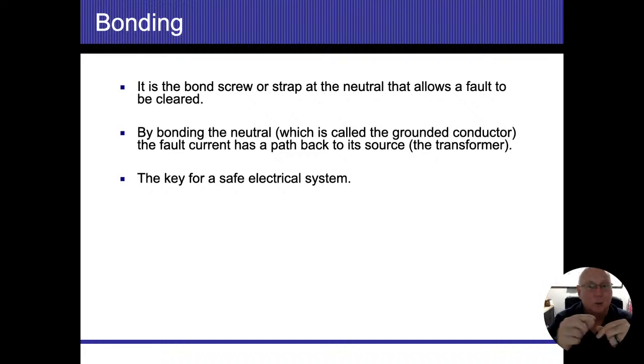All right. So there's no screws. There's no mechanical connection. They just squeezed it and basically made it into one wire. You would have to literally cut it with cutters in order to break that connection again. So if we could break a connection with a screw, it's wrong. If we have to cut it, then that splice is okay. And those splices don't have to be in a junction box.